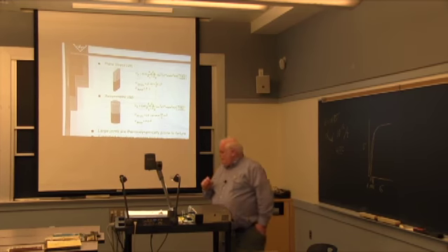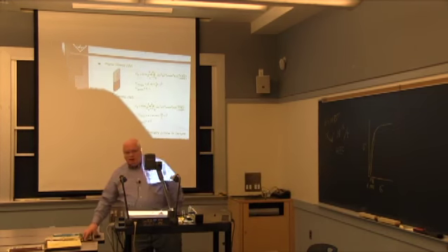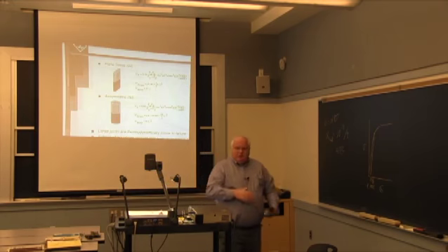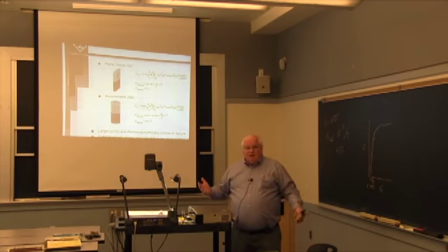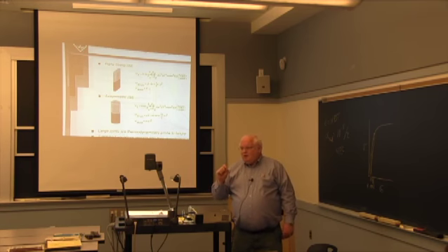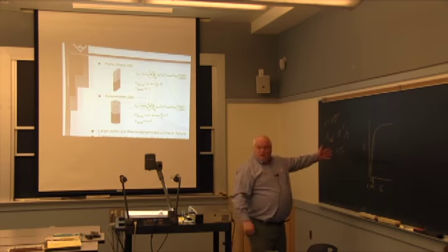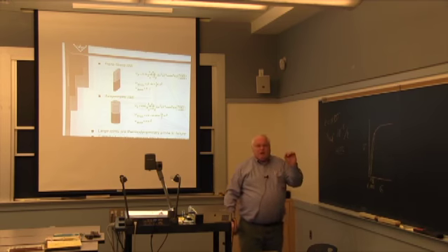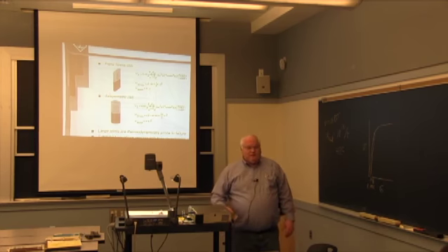Now, I think about it all the time because I spent my career talking about welding, and welding is nothing more than dealing with big thermal gradients all the time. Okay? I make an arc weld, I got thermal gradients of 1,000, 2,000 degrees centigrade per centimeter. Sometimes I got 1,000 degrees per millimeter if I'm doing laser or electron beam. Shoot, that means in 10 thousandths of an inch, I can have temperature gradients that would cause yield level residual stresses, okay?